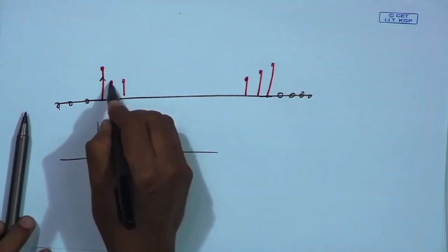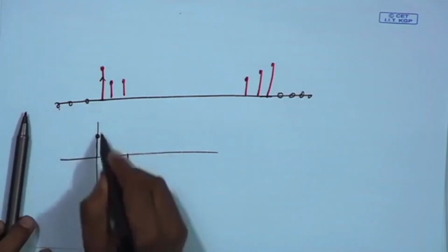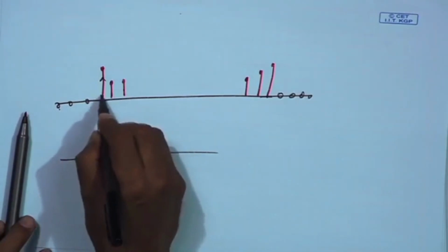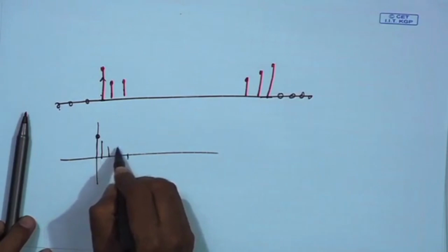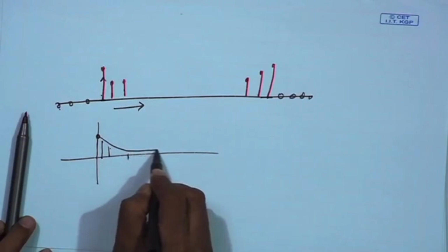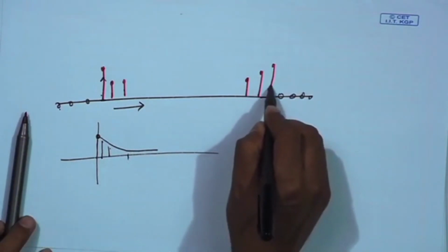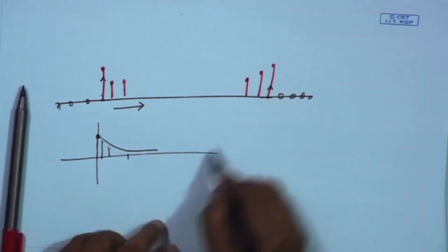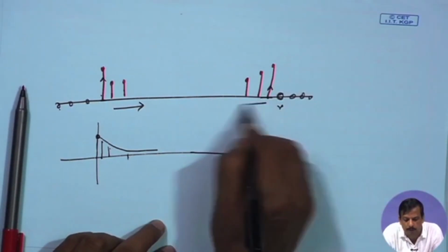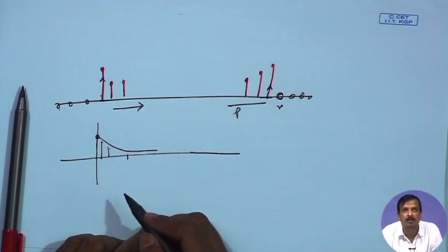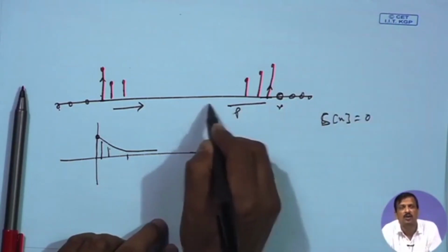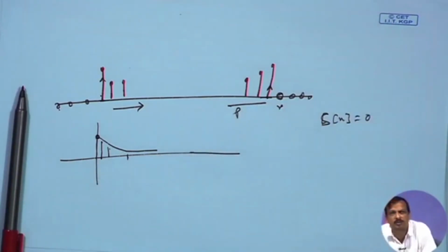I want to predict this one, all 0, but one sample is there, error will be slightly reduced. I want to predict this one from 2 non-zero, slightly reduced. So, once I go towards the window, my error will be decreasing. Once I come to the end sample, then what I want to predict is 0. This is my current sample is 0 from the previous p samples. So, current Sn is 0. So, linear combination of previous p samples cannot be 0.